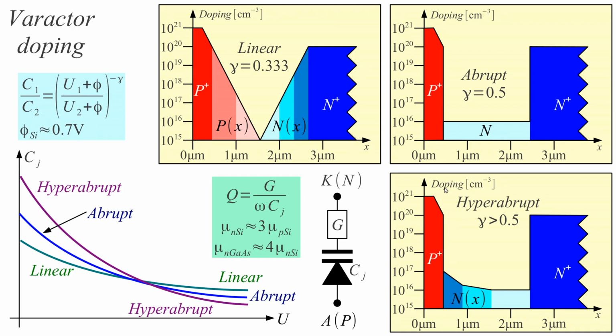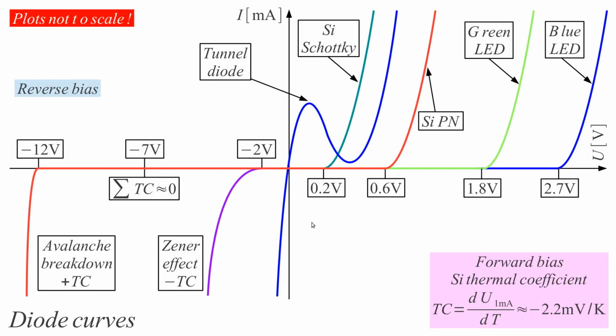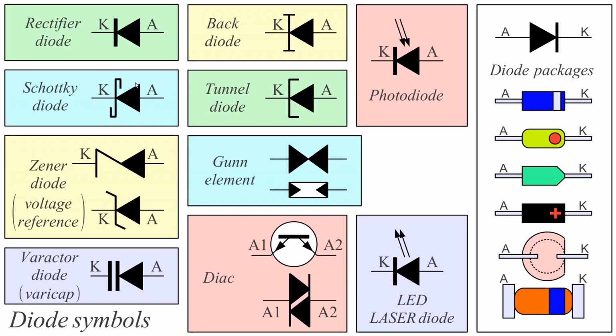If we go now to see different kinds of diodes, I would prefer to start with the reverse bias, because I already talked here about the reverse bias. So, reverse biased avalanche breakdown: avalanche diodes or Zener diodes are good voltage stabilizers. So that is what they are good for. This is not rectification really. Rectification would prefer to have the curve whole here and the curve here like this. A rectifier is the simplest application of a diode.